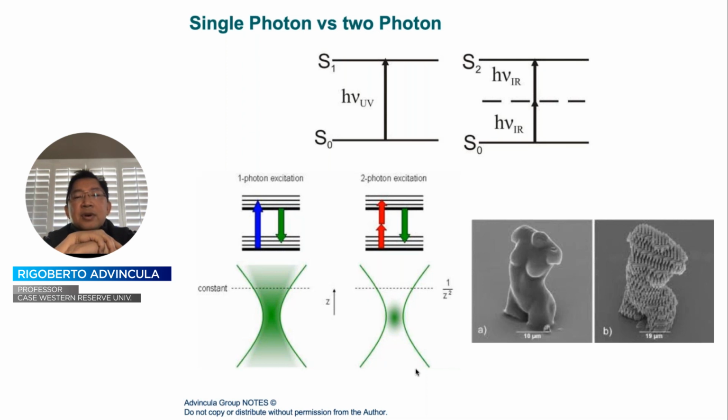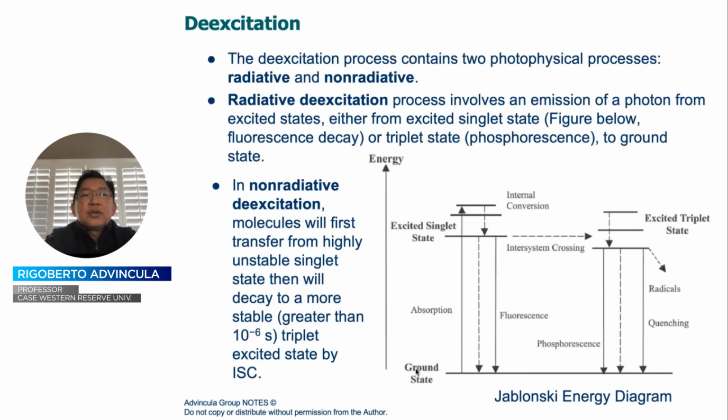In fact, my very first knowledge and example of the photolithography process based on 3D patterning is actually two-photon polymerization. And this goes back to almost 20 years ago, or more than 20 years ago rather, where the confocal microscopy and the two-photon polymerization process has been used to demonstrate nanolithography or stereolithography in this same chemistry. And some of that can actually be accessed today through commercial instruments such as the nanoscribe.